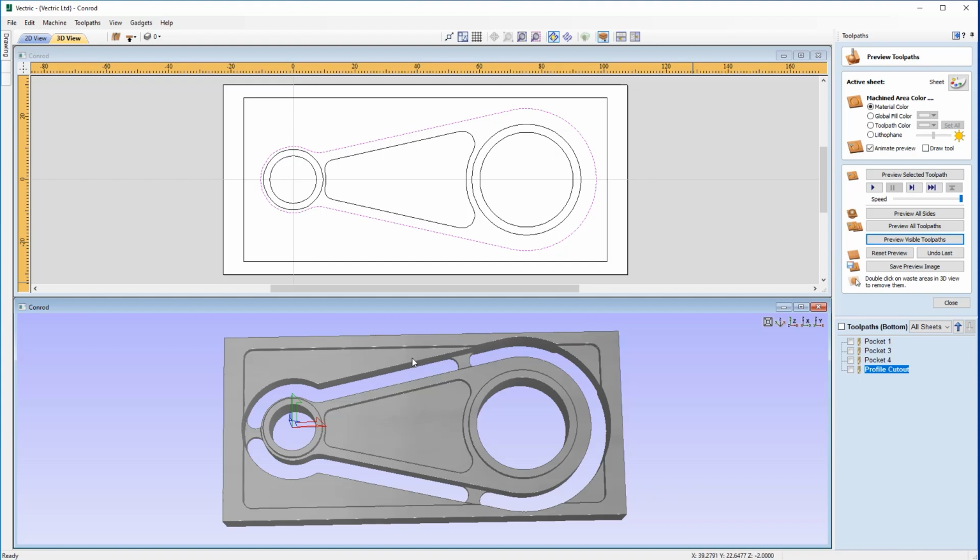So this is the depth that we've already cut away. So we've cut away 2 millimeters on this side here, for example. But this is the full 12 millimeter depth, and the tool has gone from encountering less material to now encountering more material on the side here. Now this could be a problem.